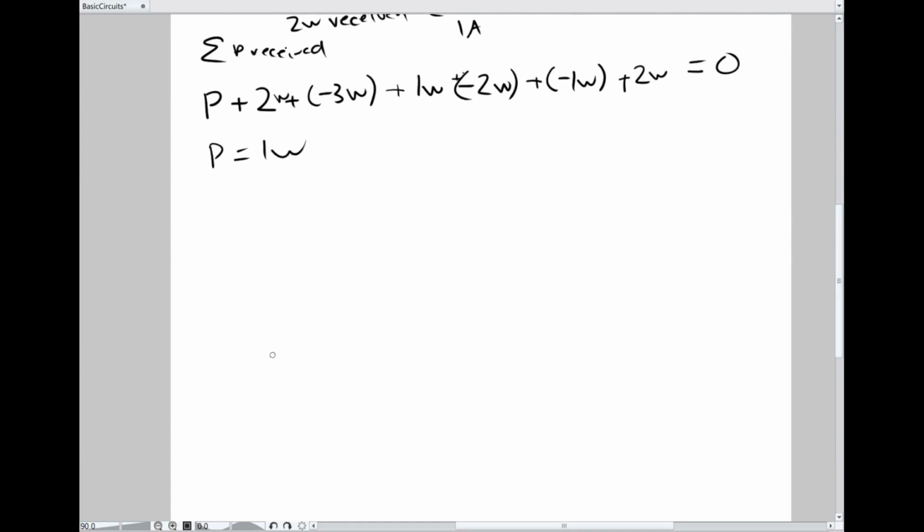Next thing I would do with power is called maximum power transfer. So this is a subject people sometimes get obsessed with, because it has to do with impedance matching into transmission lines. So say I have a resistor we're going to call RT for reasons unknown, and this we're going to call just VS. You call it VT, but let's call it VS. And then we have a resistor here we call R load, right?